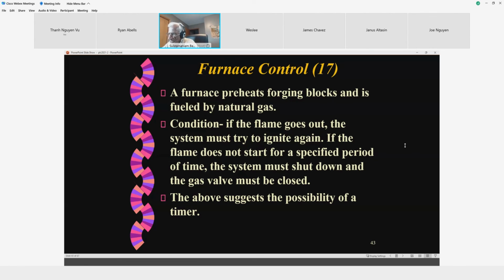Then what it does is, there is a pre-programmed time inside, but that pre-programmed time is also getting feedback from the humidity sensor. So if your clothes normally would have taken 1 hour, and for unknown reason, at the end of 48 minutes, your clothes are dry, as indicated by the humidity on the exhaust, we will shut it down, saving you some energy bill. Okay, and the level of sophistication of these systems in terms of control is becoming more advanced.